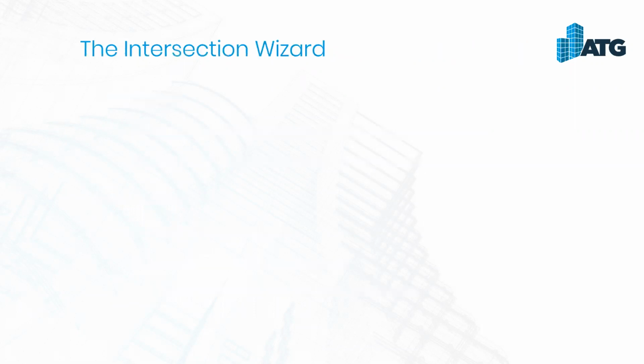So with all this in play, I want to talk a little bit about the intersection wizard before we get inside the software. The intersection wizard is a fantastic tool if the only thing that you use it for is its dynamic profile locking. I have some opinions on its ability to create target objects or a corridor for you automatically. By the fact that I'm going to go through the manual process first, I think that'll give you a hint, but I'll show you at the end and you can make your own decision. But what we definitely want to use is the dynamic profile locking.